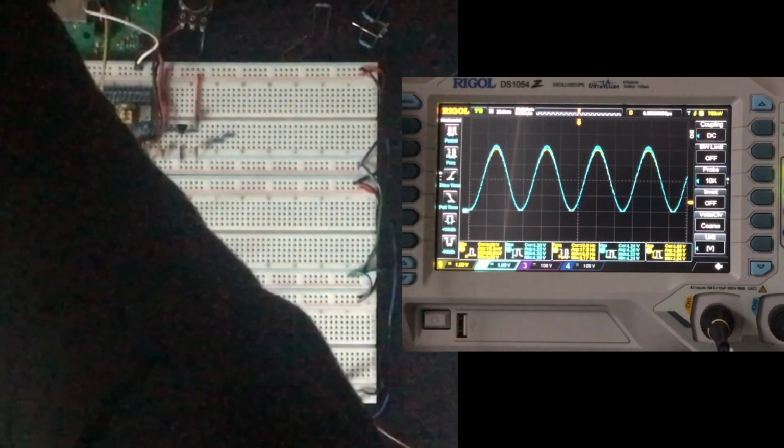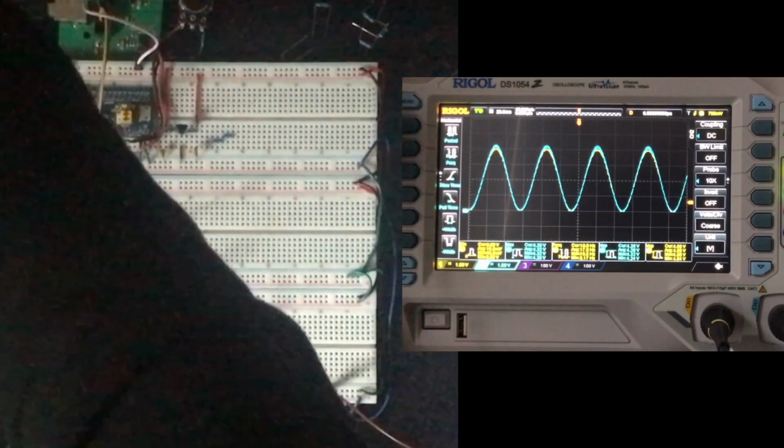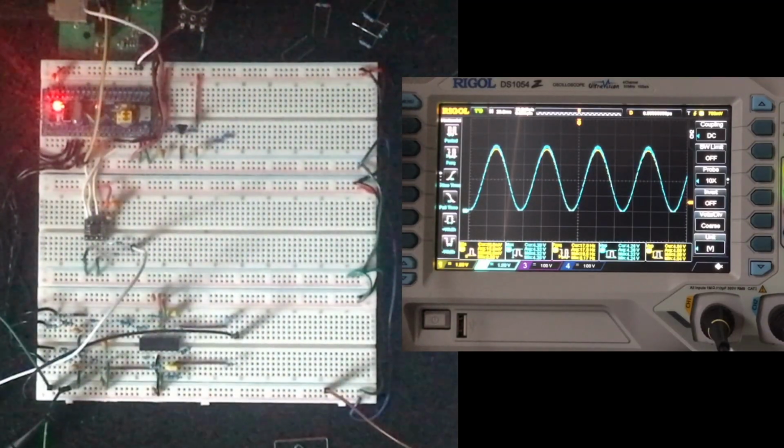So what happens here is if you have one wave of 1 hertz, that's completing one complete cycle in 1 second. If your sample rate is 44.1 kilohertz, that means you have 44,100 samples for one iteration of that loop. But what if you have 10 kilohertz?